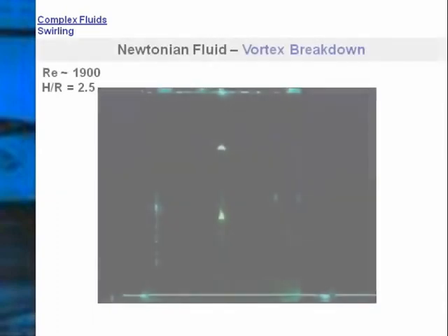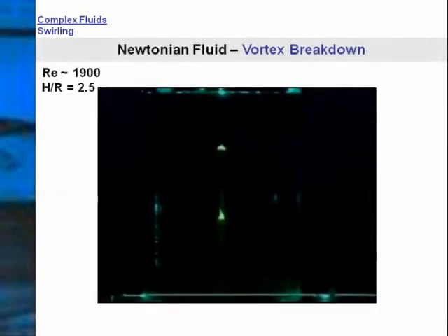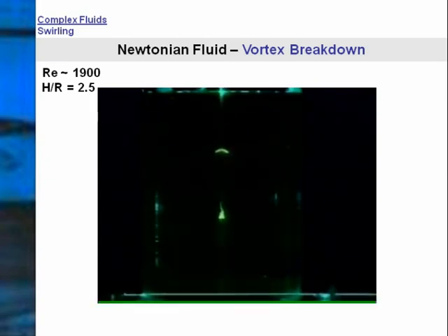Clearly, in this viscoelastic case, the flow pattern is completely opposite to that for the Newtonian fluid. Interestingly, the so-called axisymmetric vortex breakdown, which occurs as the Reynolds number is increased in all fluids, is, if anything, more dramatic in the Newtonian case. So we conclude this section with a brief glimpse of an extravagant effect in a Newtonian fluid.